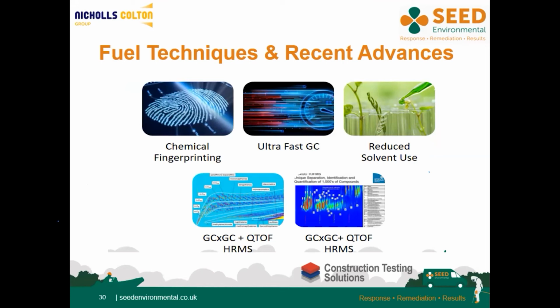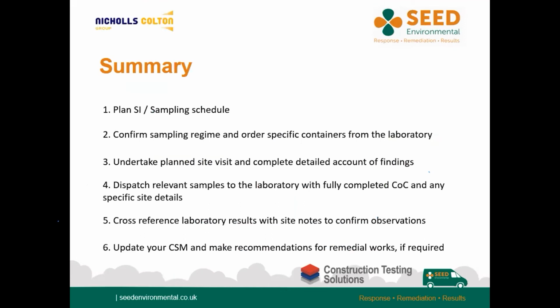Lovely, thank you, Amy. So to summarise the talk by myself and Amy this afternoon, when you're completing a phased approach to site investigations or remedial works, a fairly standardised approach can be adopted. Firstly, you need to draft a scope of works. This will include listing the contaminants that you consider to be present on site and will be submitting for analysis, and confirming how you intend to collect them.